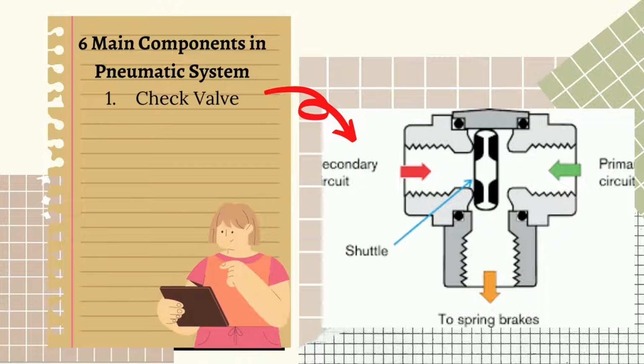As you can see from the picture, the secondary circuit is connected to the one-way valve that is installed on the hose, which connects the compressor to the buffer tank. They let the compressed air gather in the buffer tank but prevent backflow into the compressor tank.